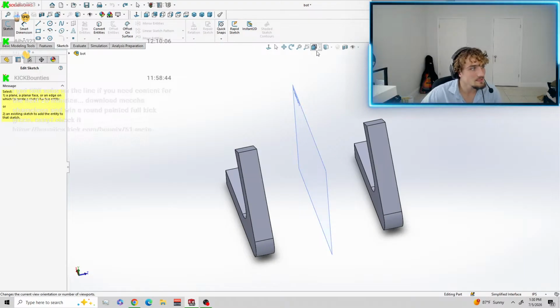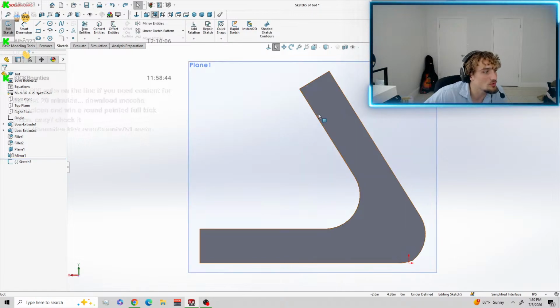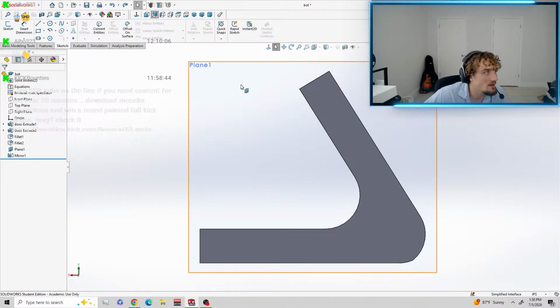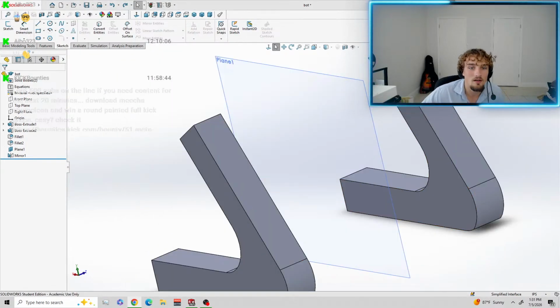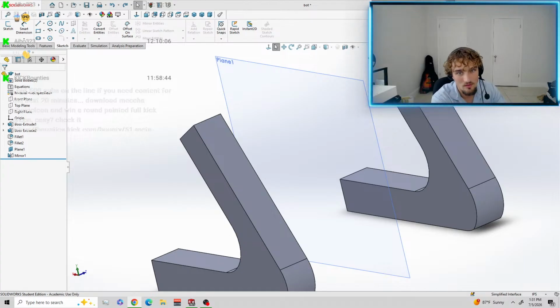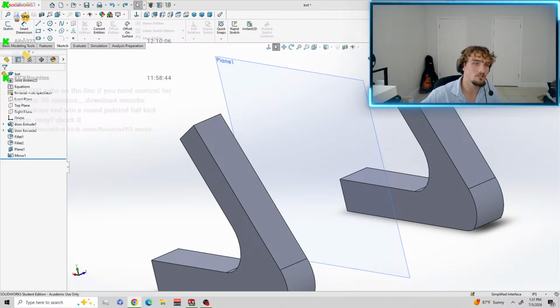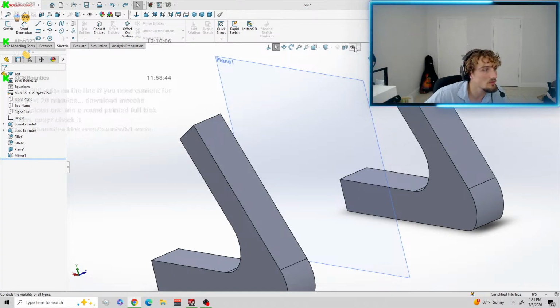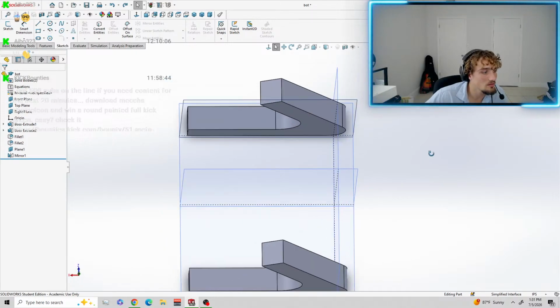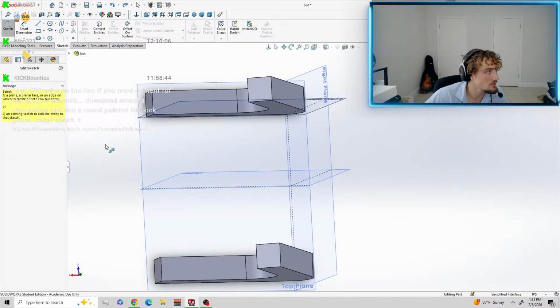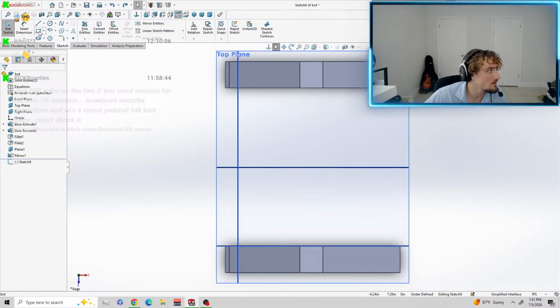There. Okay, select the plane. Why doesn't it present me with any planes? I don't want that plane. Exit sketch. Alright. How do I show planes in SolidWorks to choose from when starting a new sketch? Always see the front, top, and right in your graphics area. Click the hide show items icon, eyeball, on the heads up view toolbar. Planes. Oh, okay. Oh, that's the top plane. Okay, so now we hit sketch. Top plane. Okay, bang. There we go.